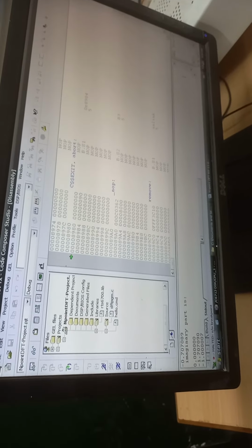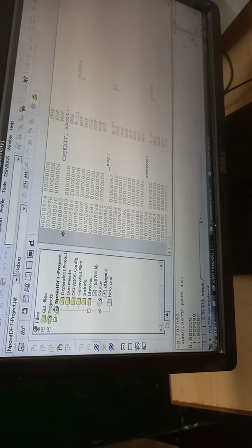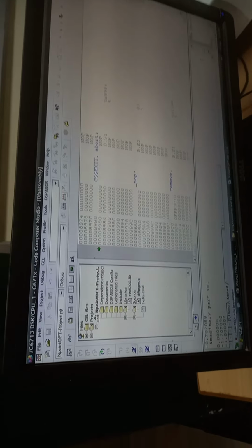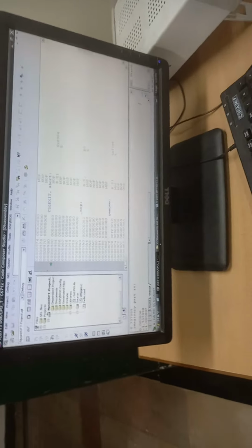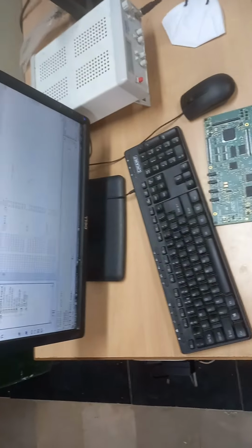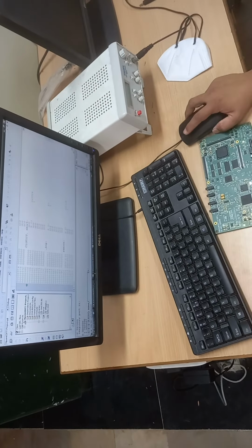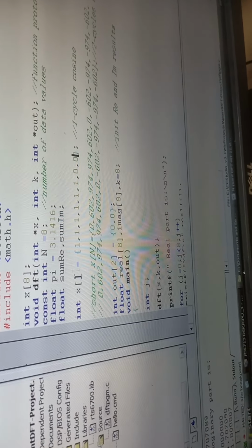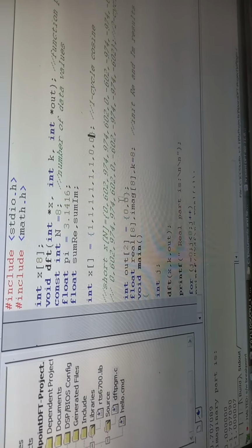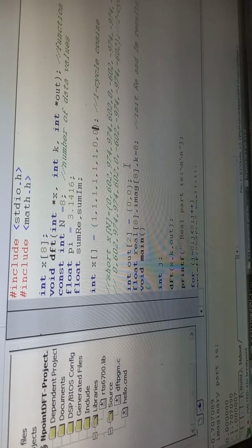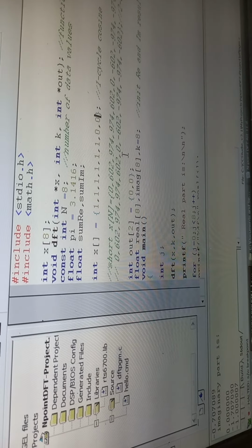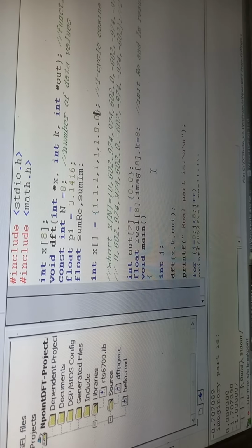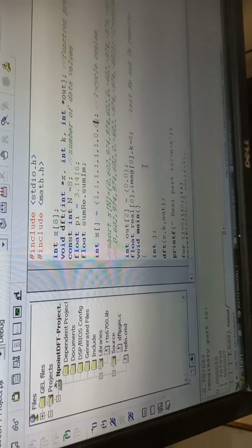You can theoretically calculate using this particular flow graph, and then you can verify the calculations. For example, you need to view the 4-point DFT of the sequence. You need to change the numbers, and then view int of x equal to 4, and then modify that particular sequence, then view the 4-point DFT of the sequence. Okay, this is your non-real-time C program for doing the N-point DFT.